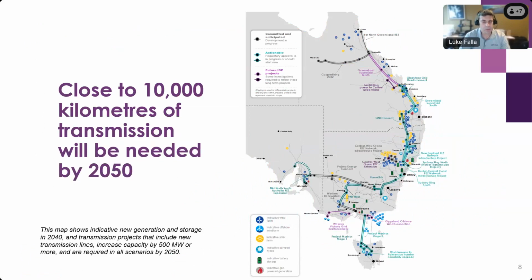At the same time as trying to do a generation capacity expansion model, we also co-optimize with the transmission network builds. And what we're seeing is there's a lot of transmission going to be needed to transport the energy around Australia. It's quite a large landmass with a lot of diversity between the different areas. You have areas like South Australia, which are already reaching over 100% penetration of rooftop and utility solar to supply the entire demand of that state at the moment. You have areas like Tasmania, which can be run by 100% renewables already, and then you have areas like Victoria, New South Wales, and Queensland, which are predominantly run by coal, and so their baseload is disappearing. So we're certainly seeing a lot of transmission requirement to bring these states together to share their resources as the transition occurs.